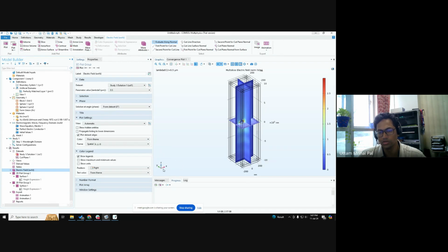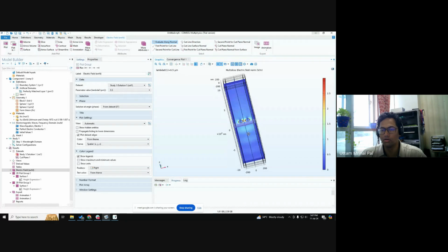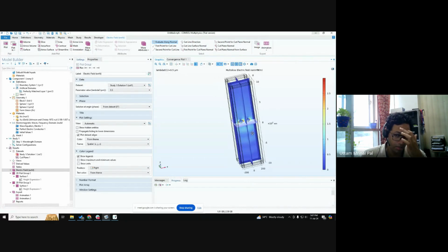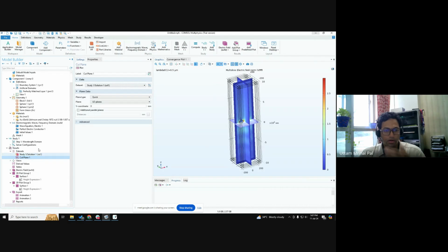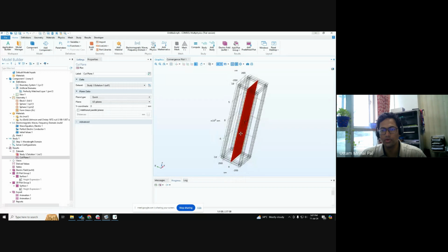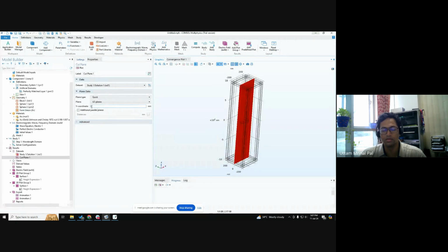So in the xz plane I can do a cross section cut like this one, because it will involve the cut of both the gold nanoparticle spheres. I make the y coordinate 0, and I can move a little bit up and down by changing the y coordinate. That will be 0 right now.